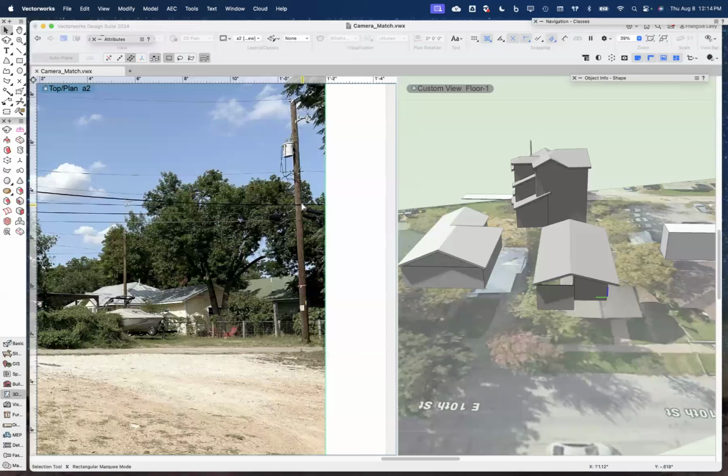But if you look at the technical criteria manual from Austin Energy, you'll know that a 45-foot pole is not 45 feet above grade. The whole pole itself is 45 feet, and 8 feet of it is buried in the ground. So don't go thinking that this dimension is 45 feet. It's actually 37, give or take.